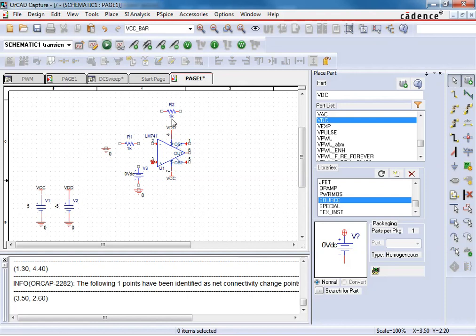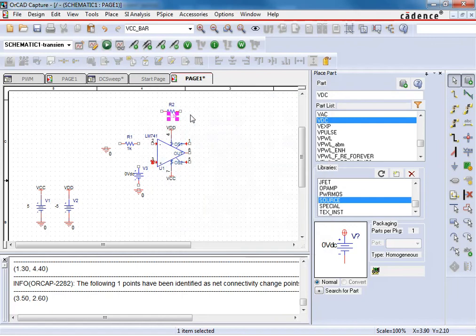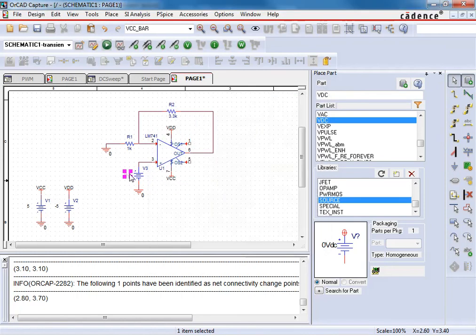Now we're just going to go ahead and connect this in a standard non-inverting scheme, and if you remember at the beginning this was a 3.3 kilo ohm because I'm going to have a gain of 4.3, and then I'm just going to run wires connecting these up with my standard feedback. And then I could put this at, for instance, 0.5 volts.